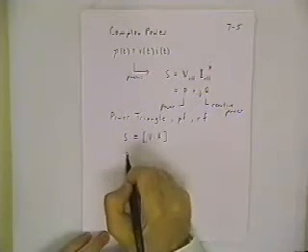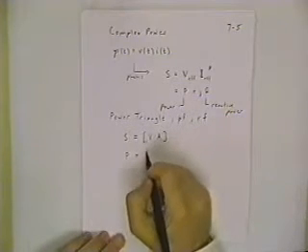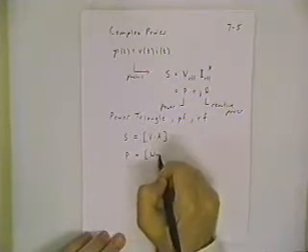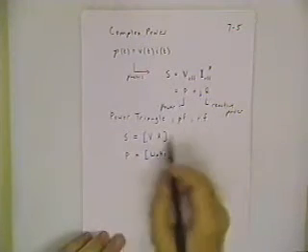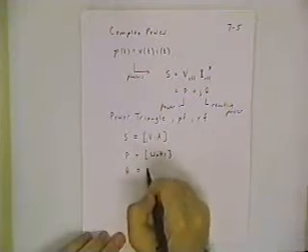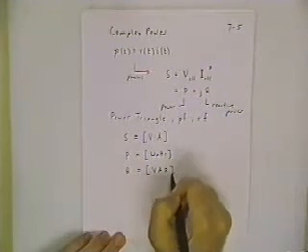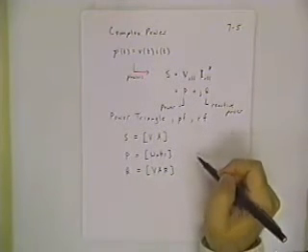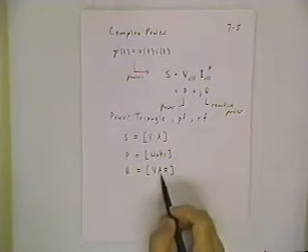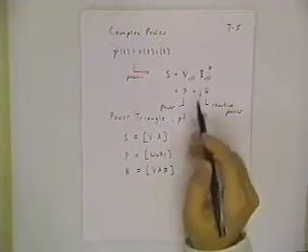When you talk about real power, or just shorten that to power, that's the power in watts that we're accustomed to from DC circuits. The Q, the reactive power, has a new special name. It's volt amps reactive. And so if you hear someone referring to a 10 volt amp reactive element, then you know immediately from the units that that's the imaginary part of a power.